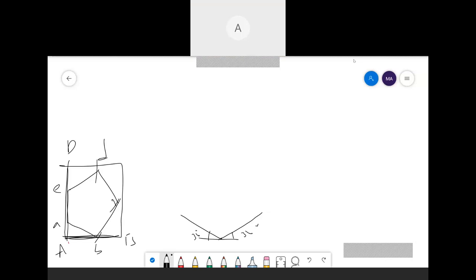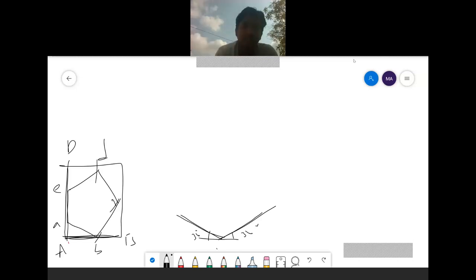So first you are drawing 30, 30. After that, I'm taking this as A. I'm measuring from A to B and cutting here. Similarly, from A to D, I'm measuring here and cutting here. After that, I will get AB and AD points.